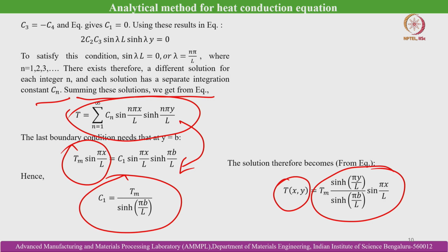But that is only possible for simpler domains. The moment there are complicated domains, as in the thermal evolution in a weld joint, it is not possible to solve for the temperature profile using analytical techniques. Then we have to resort to the numerical techniques that we have already discussed several times before, like finite element, finite volume and finite difference. Here we will show an example of a finite volume formulation, and how we can estimate the temperature evolution within a weld melt pool.